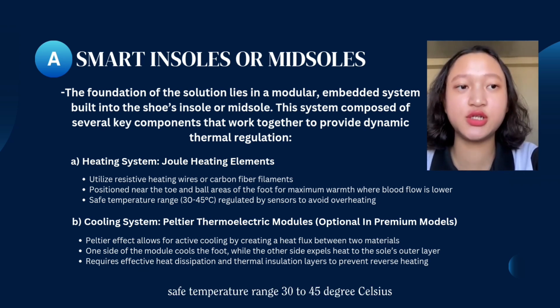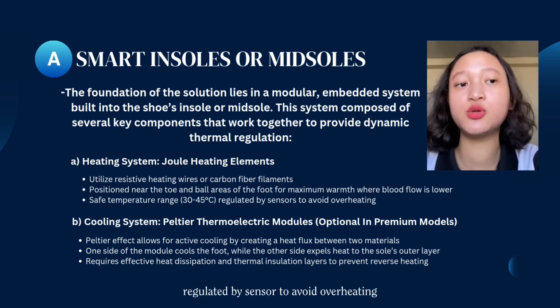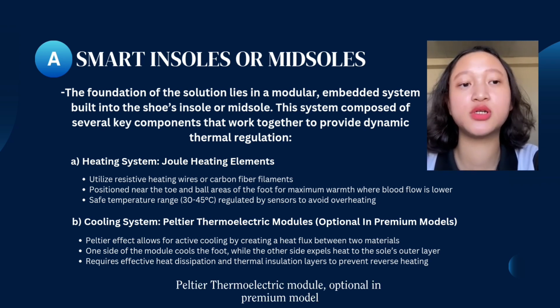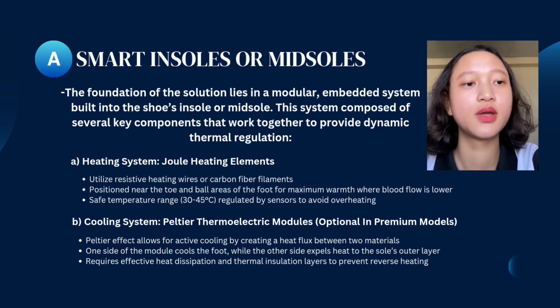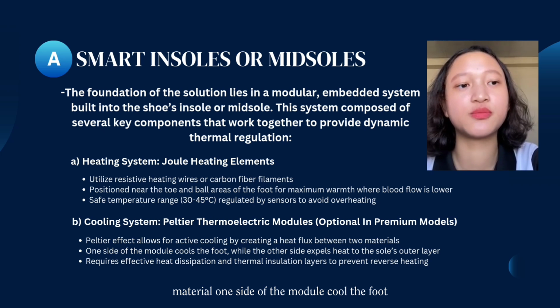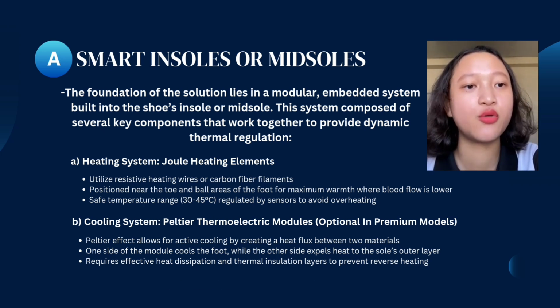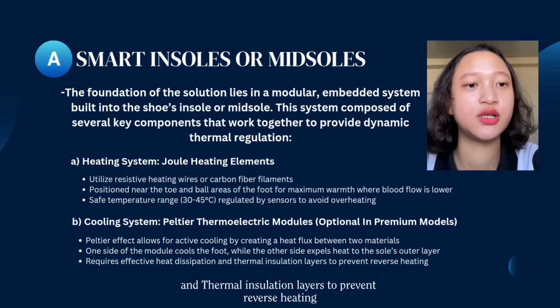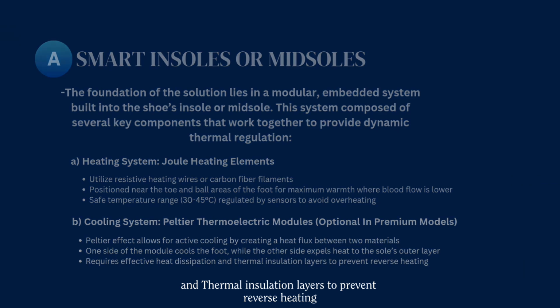Safe temperature range 30 to 45 degrees Celsius, regulated by sensor to avoid overheating. Next is cooling system, Peltier thermoelectric module, optional in premium model. Peltier effect allows for active cooling by creating a heat flux between the two materials. One side of the module cools the foot, while the other side expels heat to the sole outer layer, and it requires effective heat dissipation and thermal insulation layers to prevent reverse heating.